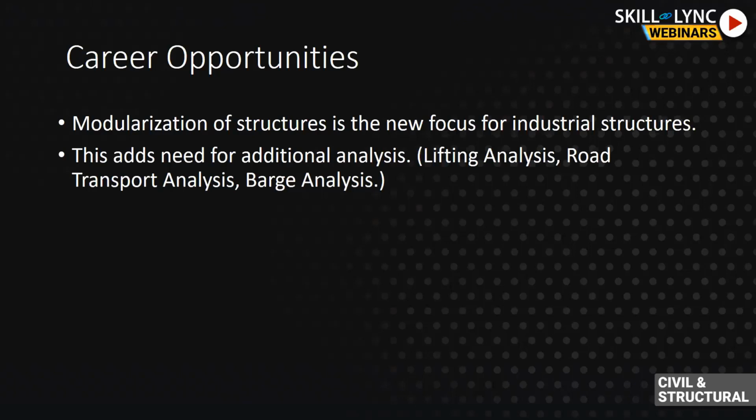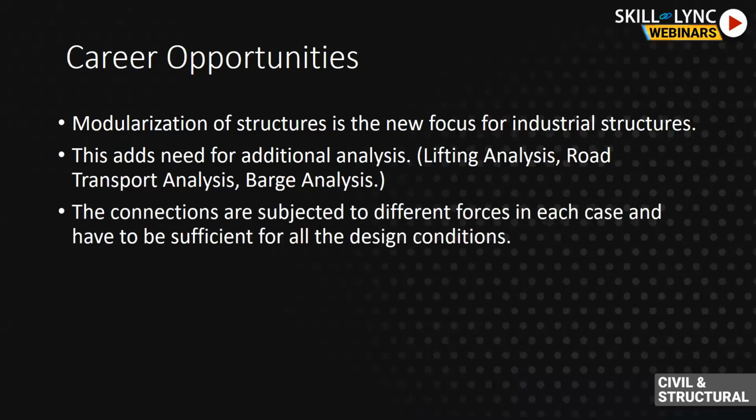So these different sorts of forces that a structure will be subjected to, the same forces will be subjected to the connections. So the connection is the same, but it needs to satisfy all the different loading conditions that will be encountered during the process the module reaches the site. So the connection design expert's role is to ensure that the connections are always safe under all these design conditions. So companies involved in modular structures have a huge requirement of connection design experts.